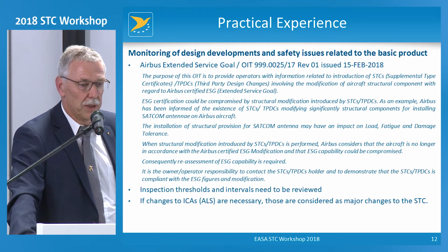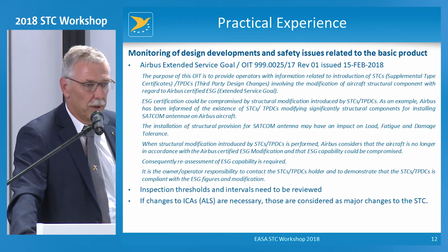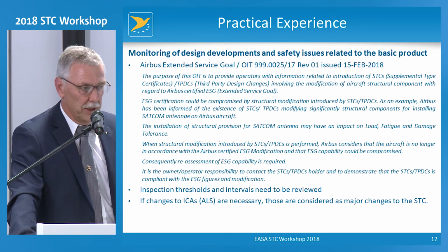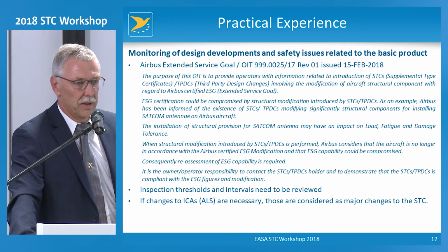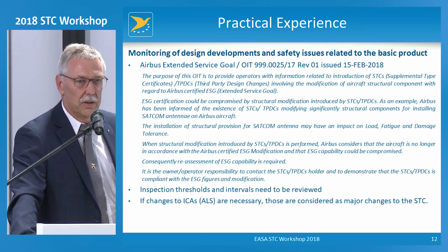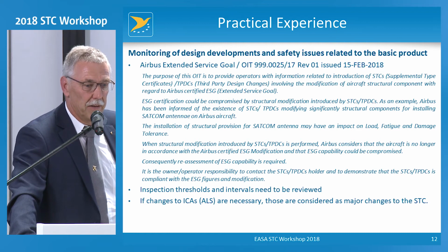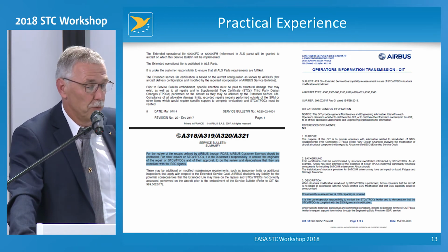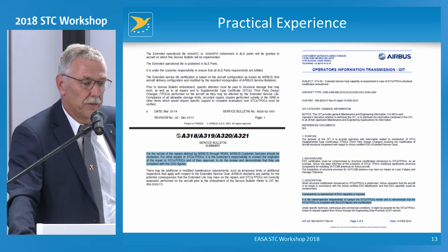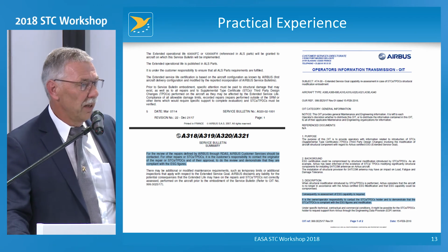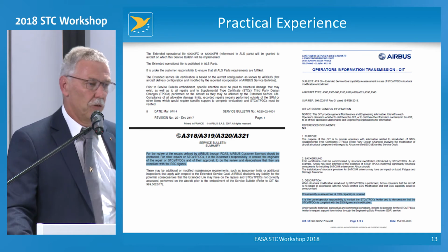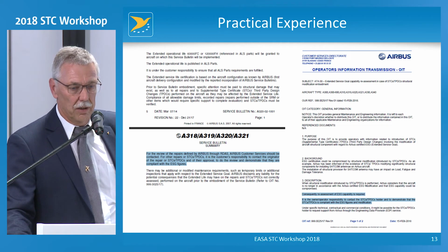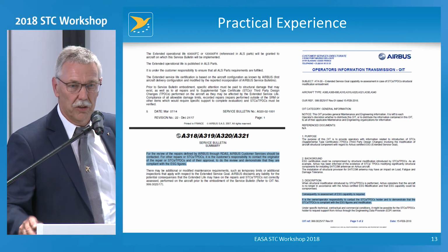However, they issued paperwork that required that STC installations that affect this airplane that is supposed to be operated for ESG need to be reviewed so that the instructions for continued airworthiness are adequate. And they issued in their service bulletin, this is hardly readable, excuse me for that, but I marked the text blue, and you will find the presentations later on, that the owner of the aircraft has to contact the STC holder and make sure that the ESG is properly covered by inspection requirements and so on.